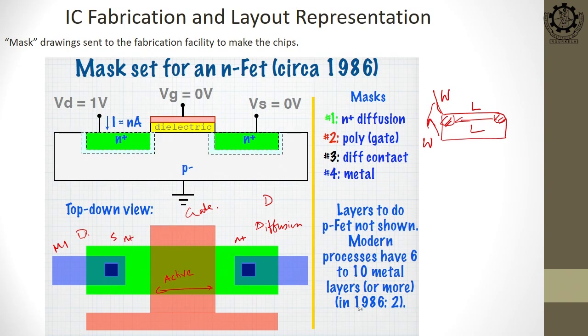For PMOS another region will be covering that, and that will be diffused with N type material. We will discuss this in case of PMOS, so you do not need to worry about that at this moment.